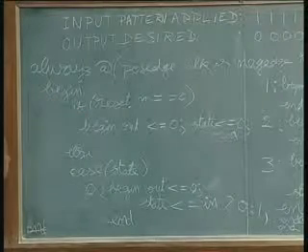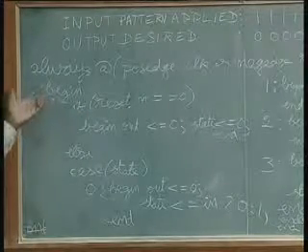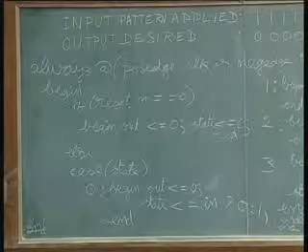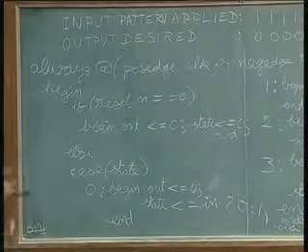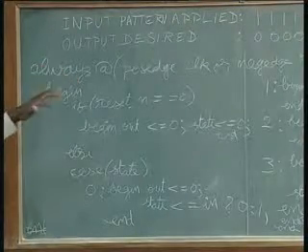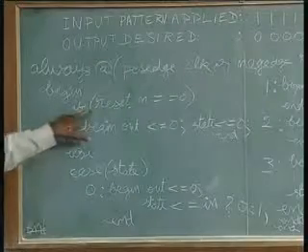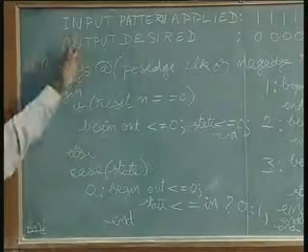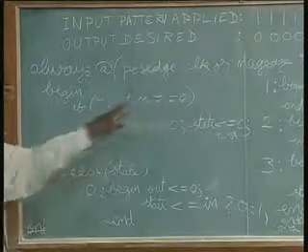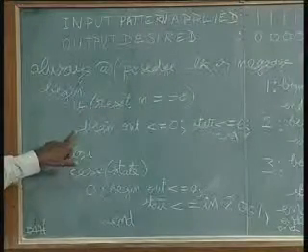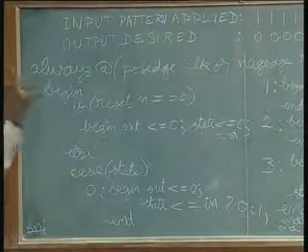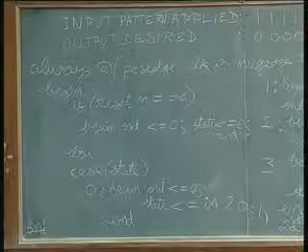So it takes you out straight away out of this always block, right. So the next action will be taken only at the next positive edge of the clock. With the arrival of the second clock pulse, once again it will see. Now let us say the reset has disappeared. What happens? This will not be satisfied. So this is not executed, and this is therefore executed only one time at the power on condition, right.